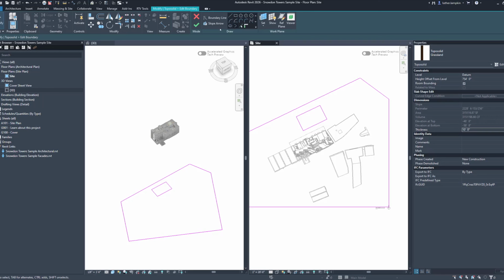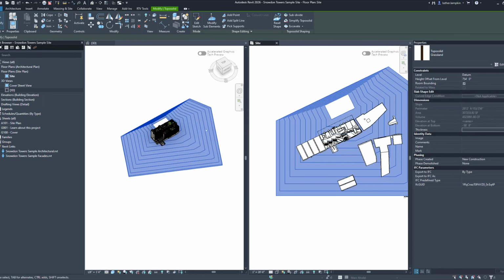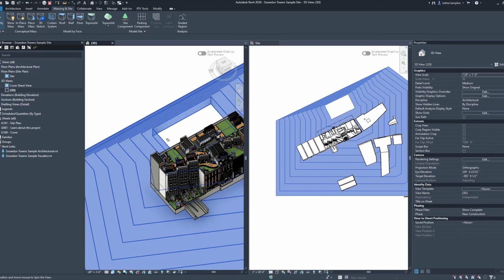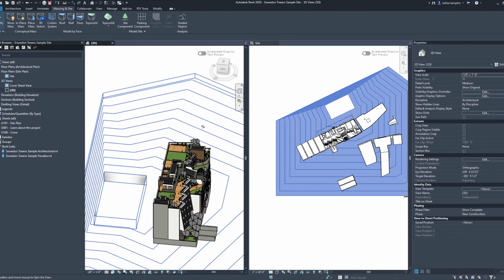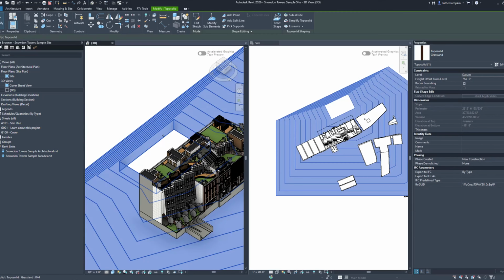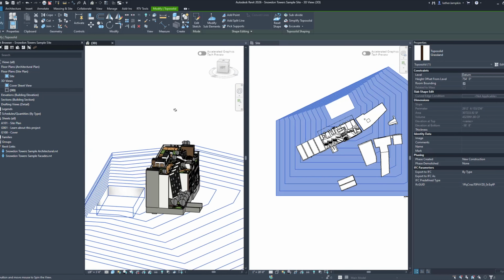All right. Okay, cool. So now I got that datum, height off level. I want to show you what's going to happen. I'm going to hit a checkbox. All right. So what you want to see now, what did it do? What did it create? Now it created this hole, right? Don't worry about what was going to happen. We're going to create something that's going to be in that hole. But what it did do is to say, hey, I can go ahead and hit split lines, pick supports. All right, that's one thing. I can create subdivide if I need to. I can excavate. And we're going to do it. I just want to show you, look how the topography changes based off of what just happened.